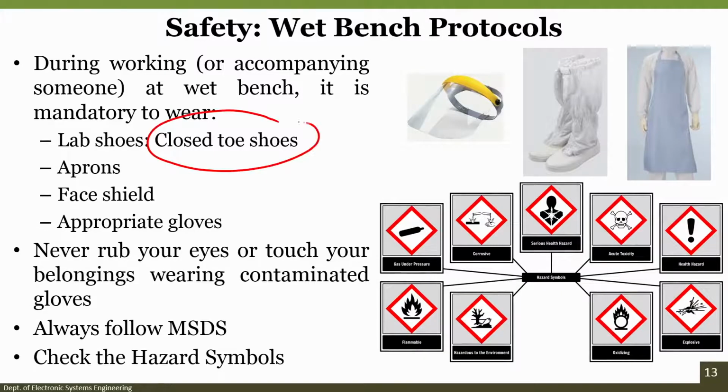This is extremely important. Whenever you work in a clean room environment, you should wear closed toe shoes. Aprons, face shield, appropriate gloves, and the most important thing is you should never ever touch your eyes or your belongings with your contaminated gloves.